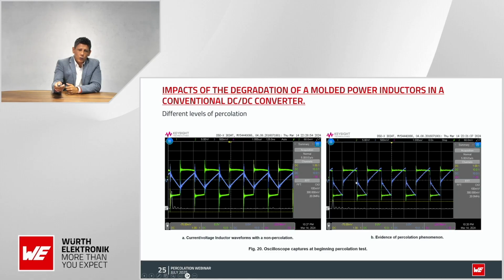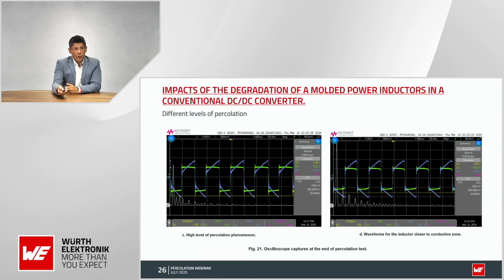If we move a little further, we see an increase of the harmonics. But wait, the jitter here decreased. Comparing this point, we almost have no jitter. The one that is increasing is the step, and we have a huge amount of harmonics. That is something we are concerned about. Why do we have this huge amount of harmonics? For sure, our model before represents a resistance, so it's a step, and a step in terms of Fourier series means an infinite amount of harmonics.